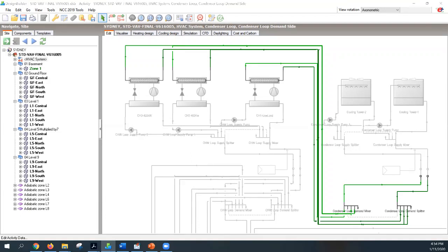Okay. So we have 4 to 5 questions that have come in. So I think we'll take them one by one. The first question, PC, is can we import the models or drawings from SketchUp or Revit to DesignBuilder? You can. You can't do a direct import from Revit, but you can export Revit to GBXML, and then you can import the GBXML to DesignBuilder.